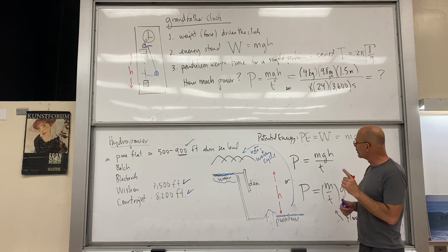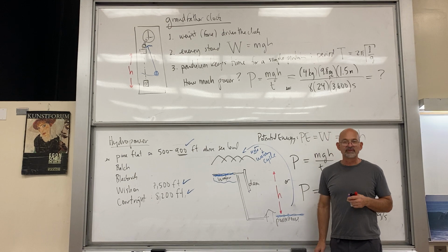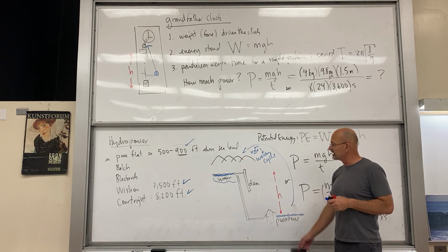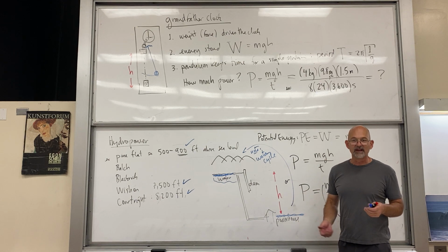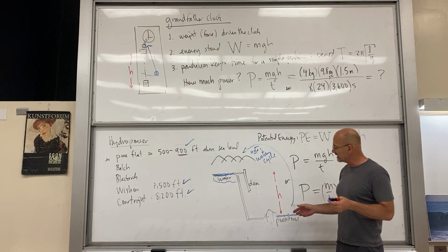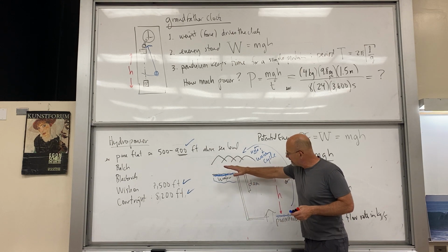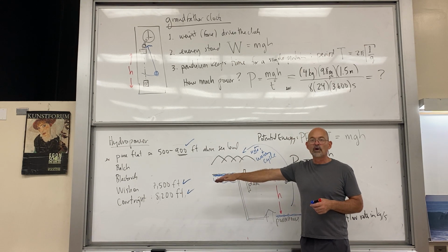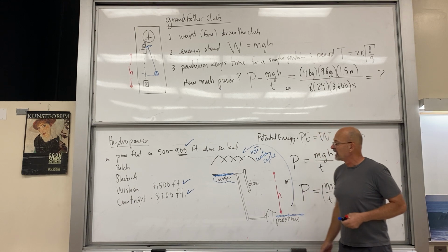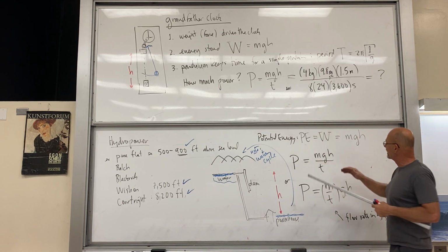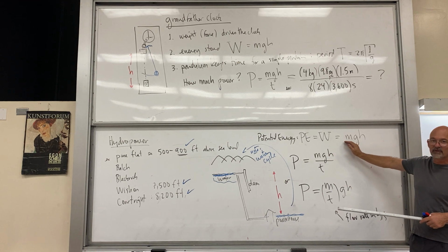Except there's a second way for the water to get up there, and that is called pumped storage. So the lower powerhouse may actually buy energy from somewhere else where it's not being used, at night for example, and they will pump water up the hill into the higher lake as a form of energy storage. And we talked about energy storage in the past, where we said if we could just store that work, it would be potential energy, it would be stored work.